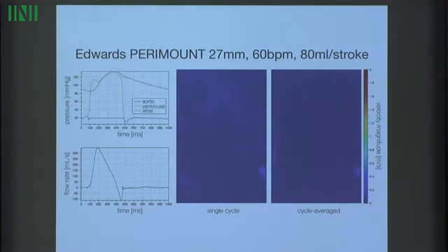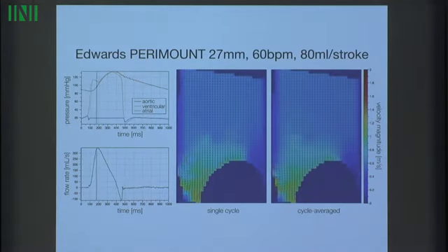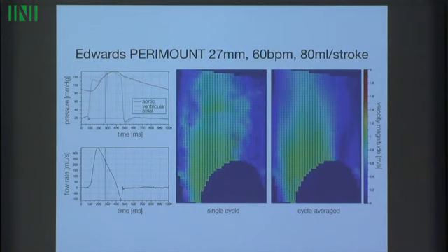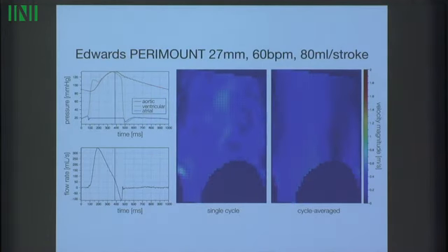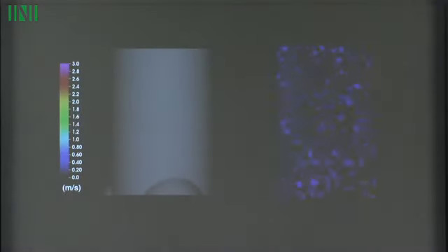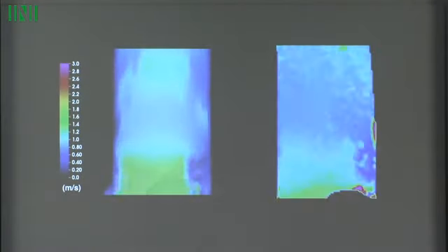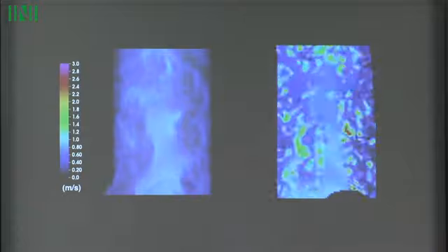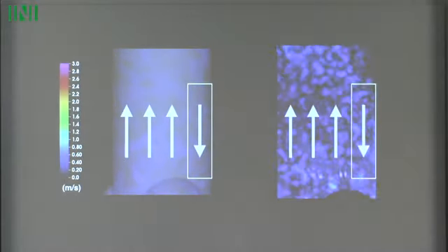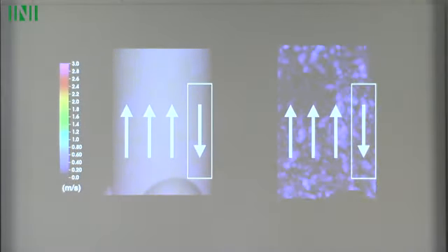We're doing quantitative flow visualization here in order to start to quantify the agreement in terms of the flow patterns. And so this is just an example of some data that we've acquired using a technique called particle image velocimetry, and have some reasonable qualitative, semi-quantitative agreement in terms of the computational experimental results.